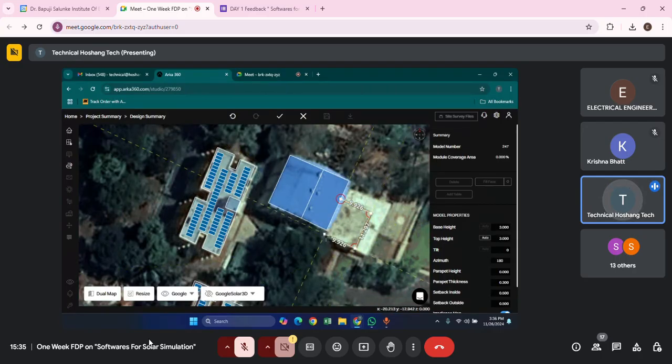While you visit physically, you must get these dimensions in meters. For calculating, you can use either a manual tape, or nowadays we have laser length meters. They use laser and infrared to calculate the length of the building. So easily you can calculate the diagram, and you can have a rough layout of whether any obstructions are there or not.